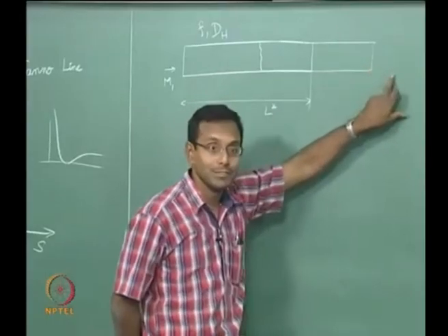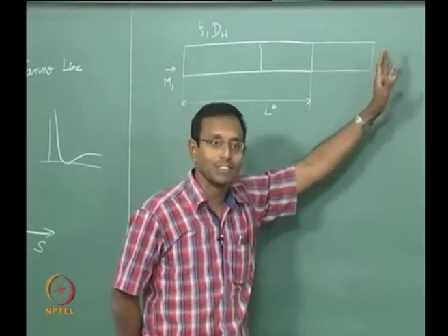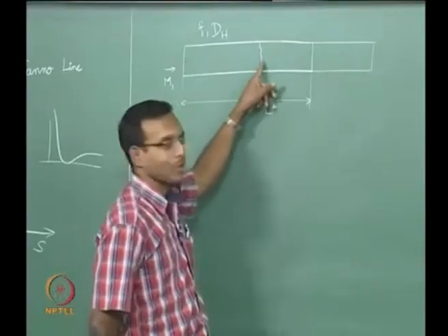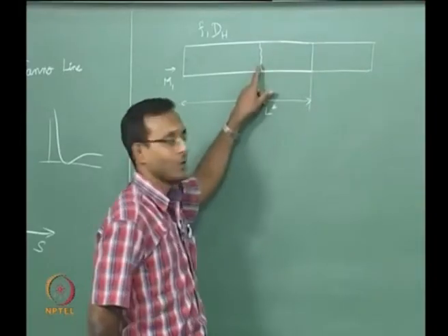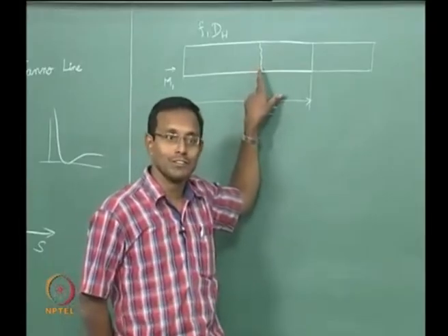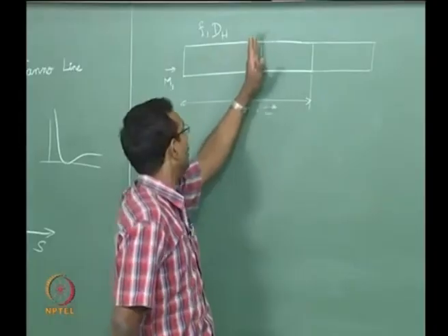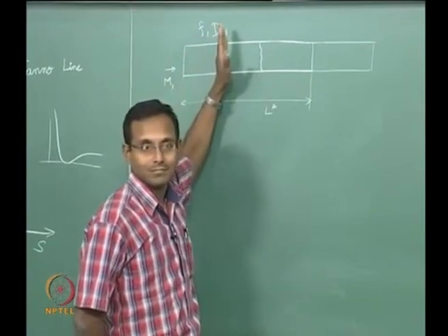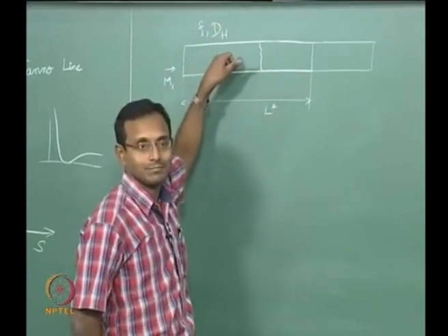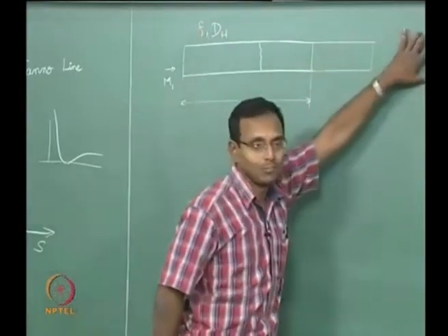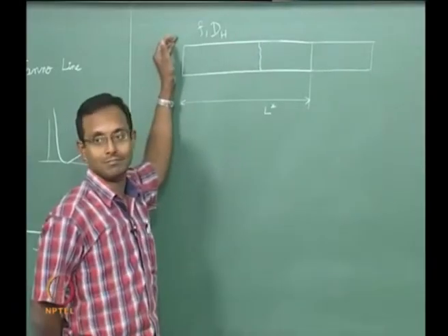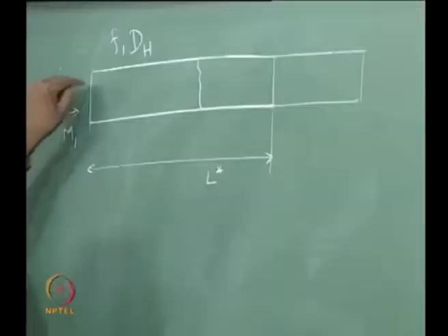If I increase the length further, what happens? One more compression or set of compression waves that travel inward, because it is again retarding. Now, it is going to go all the way up to here because it is all subsonic flow. It will come and reach this point. Now, the set of compression waves is much more strong. So, they can run against this flow a little more. It will go and stand where again the new Mach number of the shock will match the incoming flow and it will stay there. Okay. Shock would have run a little more ahead. Okay. It will go in if I increase my duct length more. And of course, if I keep on increasing the duct length, there will be a point where the shock will go sit outside this. And then I have only a pure subsonic problem inside this duct. That can also happen.